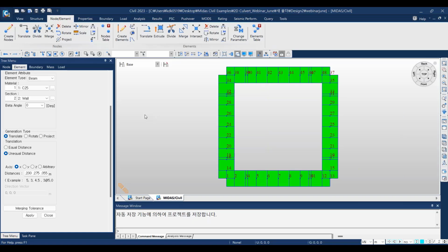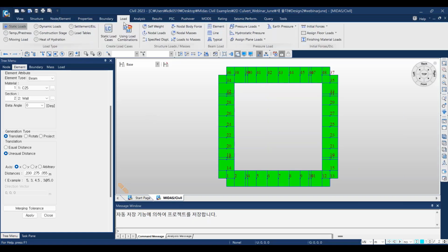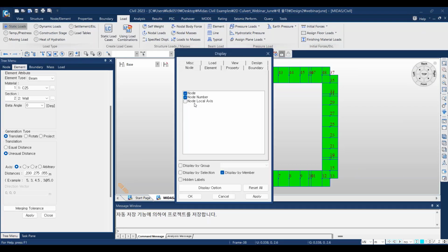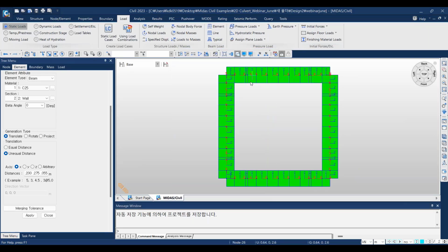The next step, we need to define the loading condition. Before reaching to the loading condition, you can check the element axis, so we can see if they are properly set. If you check this axis here, you can realize that we have Z in this direction here, and we have Z upward like this one. For the upper slab and the left wall, Z is in the direction that we want to get the result.